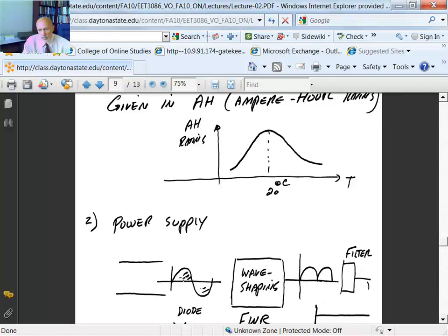If you take this signal right here and hook it up to a DC voltmeter, it will indicate 0, because all DC meters are calibrated to read the average value of a signal. And the average value of this signal has plus and minus parts that cancel each other out, so it reads 0.